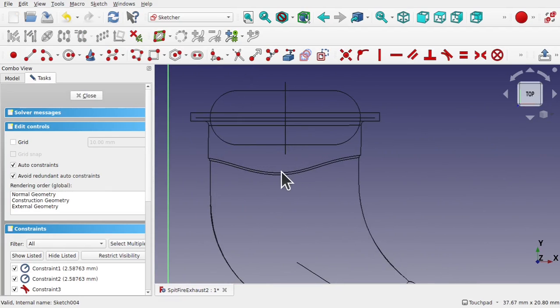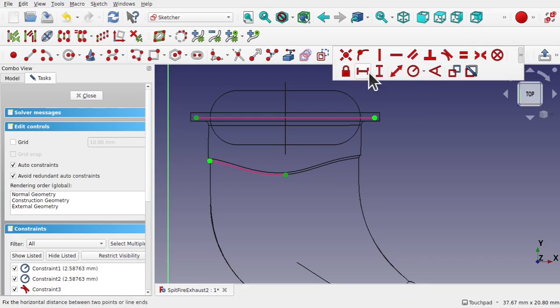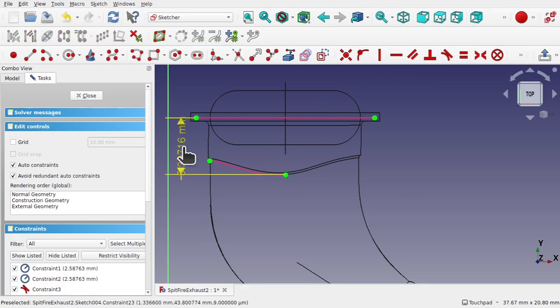And we need to bring in this top part here. Use the import geometry, pull in that line, and we'll pull in the top part here. There is a vertex sitting here, but I don't think it's the highest point. So let's bring that in. Matter of fact, that is the highest point. And then we can make a measurement between these two, placing in a height. Gives us some reference. 5.39, 5.4.